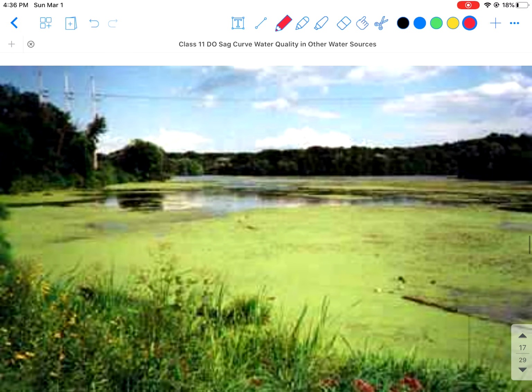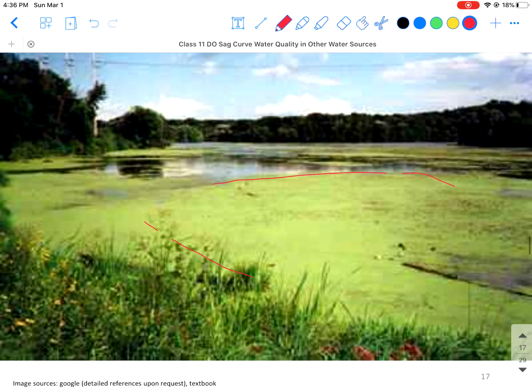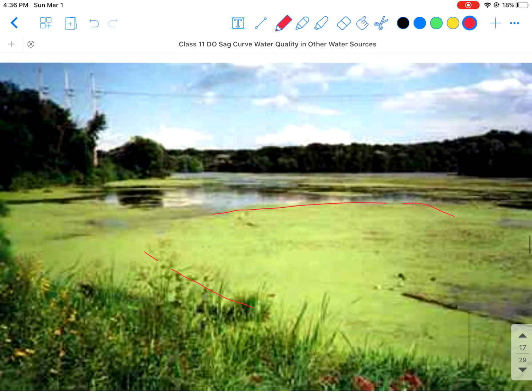Okay, so you can see that the phosphorus will cause a lot of algae to grow on the surface of the lake. So first, they will cover the sunlight and basically reduce the oxygen that's generated in the lake water. And once they die, they will form these organics and further form sedimentation. And these organics will serve as a BOD in the water. And this is going to significantly reduce the dissolved oxygen in the water. Okay, so that's a burden to the water quality.